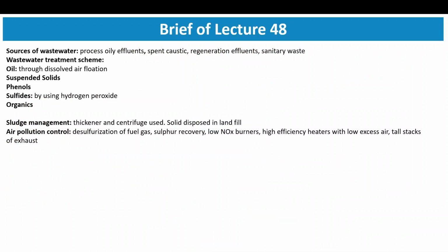So moving forward, you can say that the sources of wastewater in this plant usually have much higher BOD and COD because it deals with organics. So it will have oily effluents, spent caustic, regeneration effluent and sanitary waste.